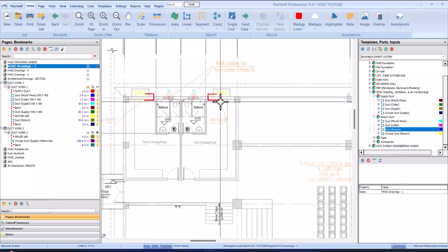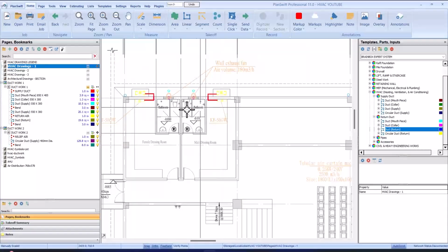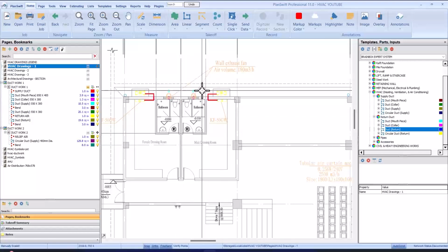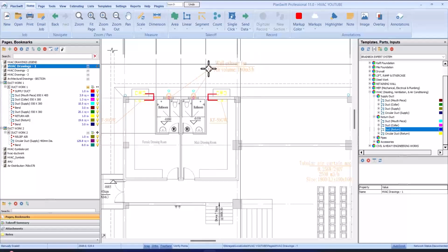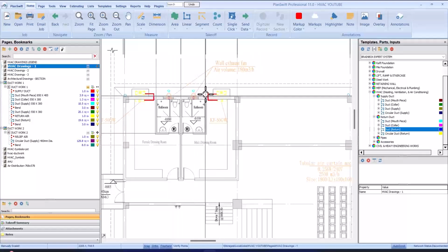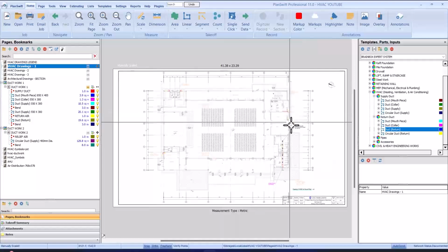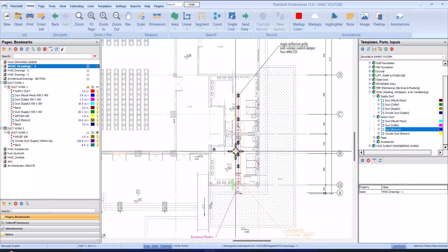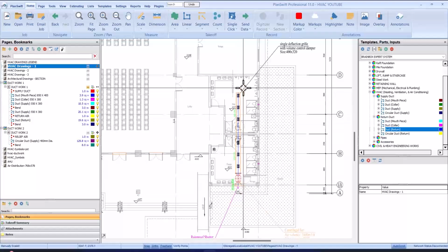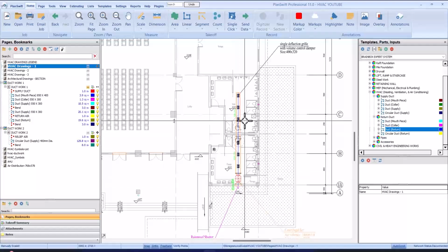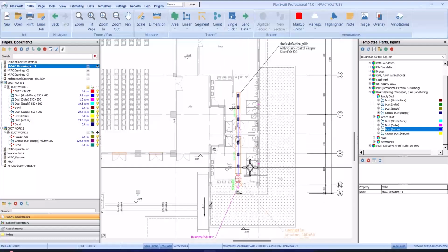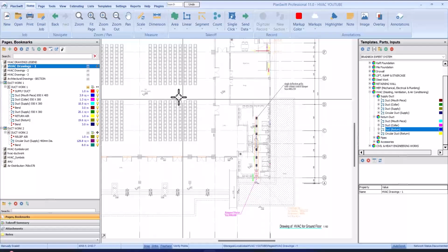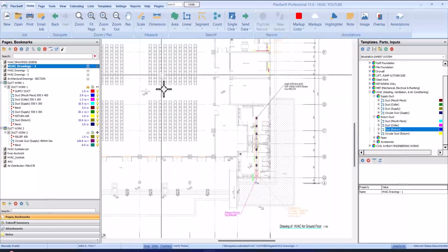In this HVAC system, the only thing required is cooling and then extracting the waste air outside the building. As you can see here, wall exhaust fan. Extract the waste air outside the building. And also here, we have a ductwork with a volume control damper with fan that extracts all the waste air, foul air, within the toilet area outside the building, so that it will not contaminate the air in the hall. This is a multipurpose hall.